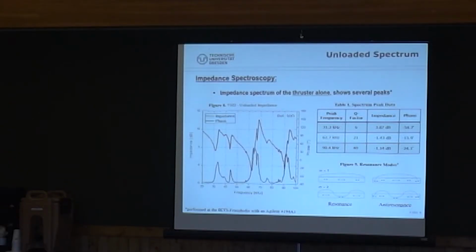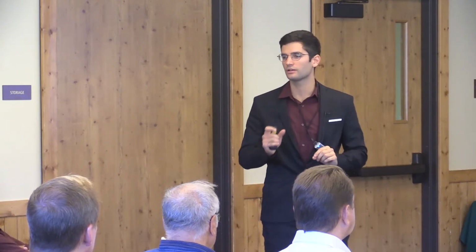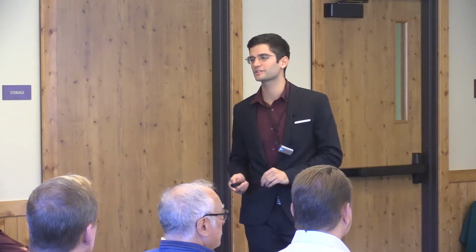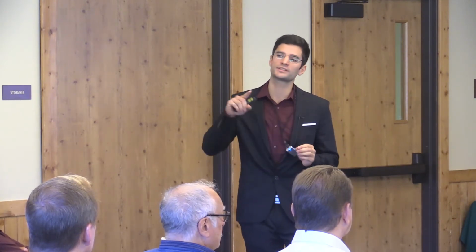There's the other diagram where you turn things on and you see the thrust. Is this over that whole cycle? Oh no, that's different, because the diagram that I showed is a pulse that's performed by Woodward, so that's a fixed frequency. And what I'm doing here is varying the frequency that I'm driving the piezo actuator at, to see how it responds, how the impedance is at a specific frequency. It's a sweep. The thrust that I showed in my first slide is from Professor Woodward. It was an example of a pulse at a fixed frequency.